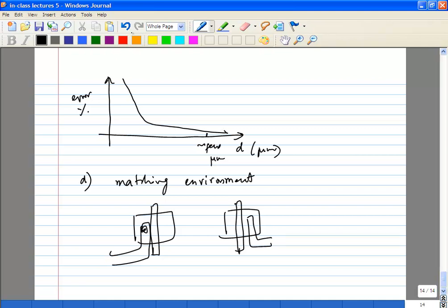So that at least, for example, there will be overlap parasitic capacitance from the metal line onto this. So you have to worry about matching capacitances in an RF sense. Or you could, for example, have a supply line, let's say VDD, running all the way here. So you'll probably want to extend it. Very small things like this can make a big difference. So if you want to match 2 things, try to make as many things as possible identical between those 2.